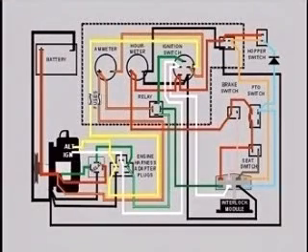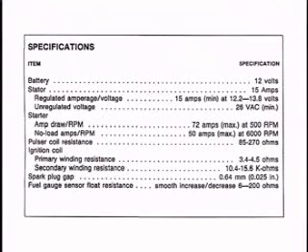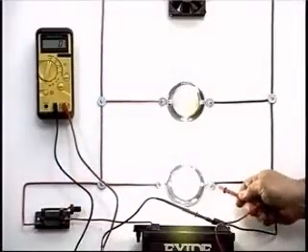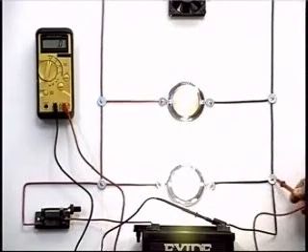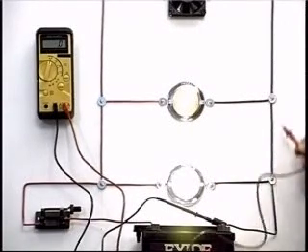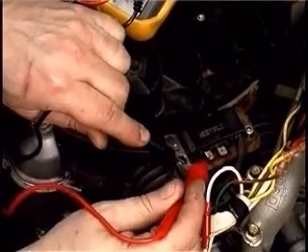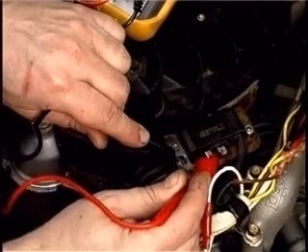Circuit diagrams and specifications are a key element for successful circuit testing. Using a diagram or schematic helps the technician identify all parts of a circuit and the location of logical test points. Specifications, especially for current draw and resistance, are necessary for complete analysis. Observing the basic theory which has been illustrated and following basic test procedures as demonstrated are necessary steps in the successful diagnosis of electrical problems. Applying these principles in advanced training programs will make analysis of more complex systems easy and accurate.